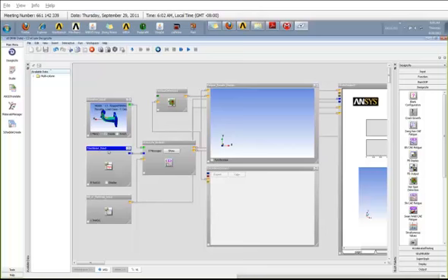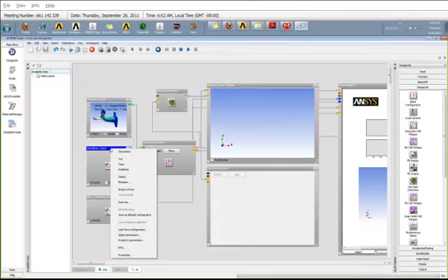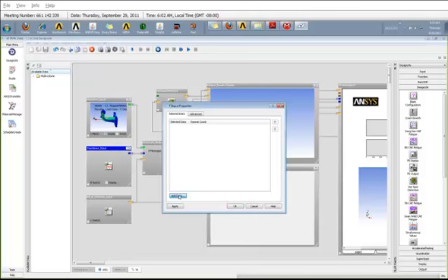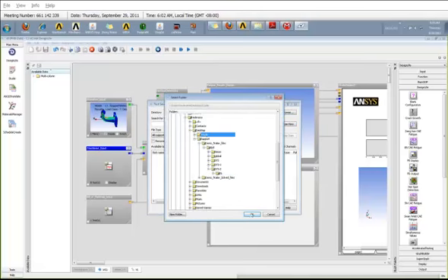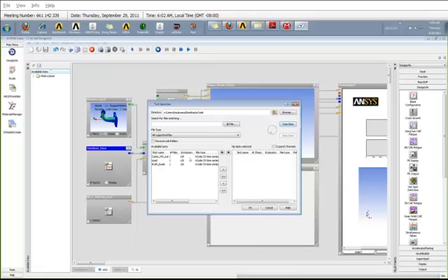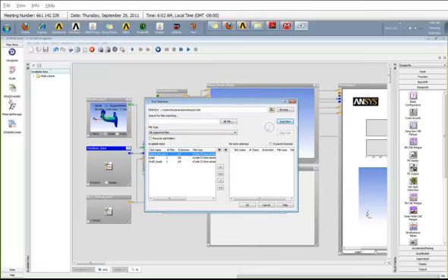Let's go to the time series input. Currently, I don't have any time series input, so I'm going to go ahead and add it. Again, it's the same thing. You would right click, go to the properties, add data. In this case, I'm going to browse for my load files. I'm going to scan it. Then that is the load file that I'm looking for. It comes with an extension S3T. If you have any load case files in a text file or a WordPad file, you can change it using this ASCII translate on your left-hand side.